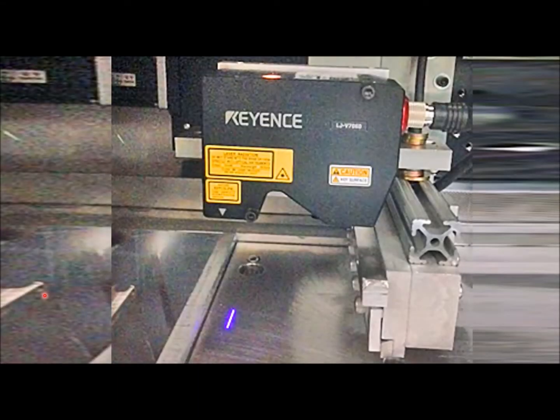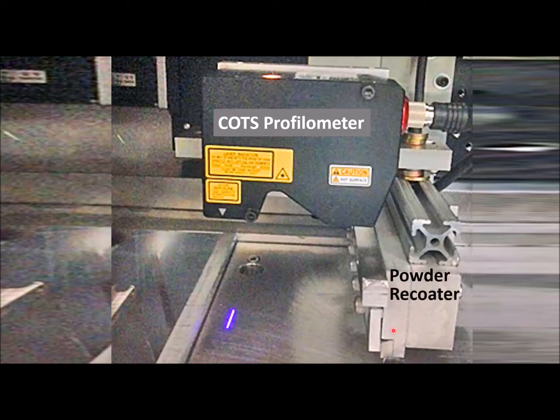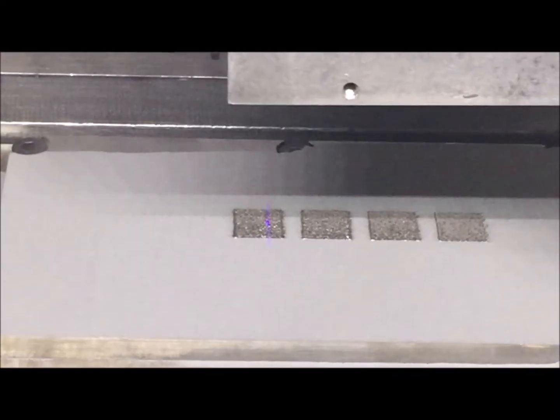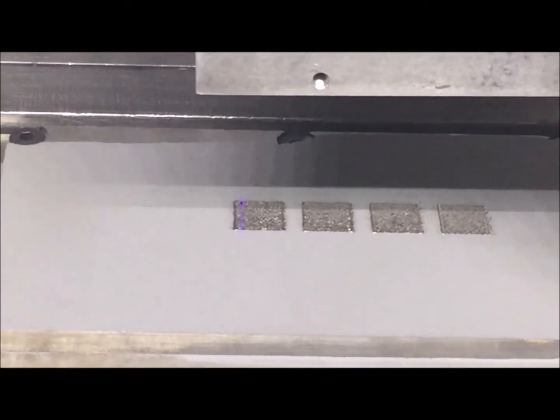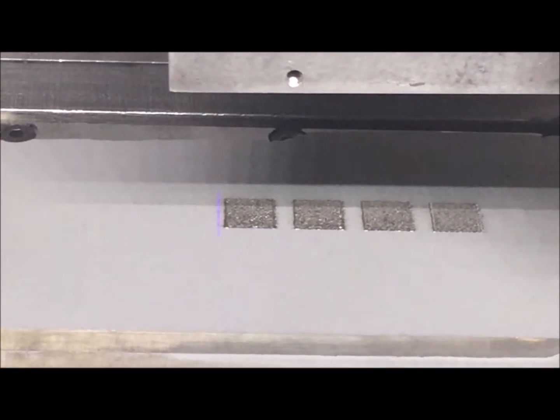In earlier work, the profilometer was mounted to the powder recoater arm. The line sensor generates an area scan due to the motion of the recoater arm, which occurs at the same time and in front of powder coating. By scanning in parallel with powder coating, no additional cycle time is added to AM fabrication.